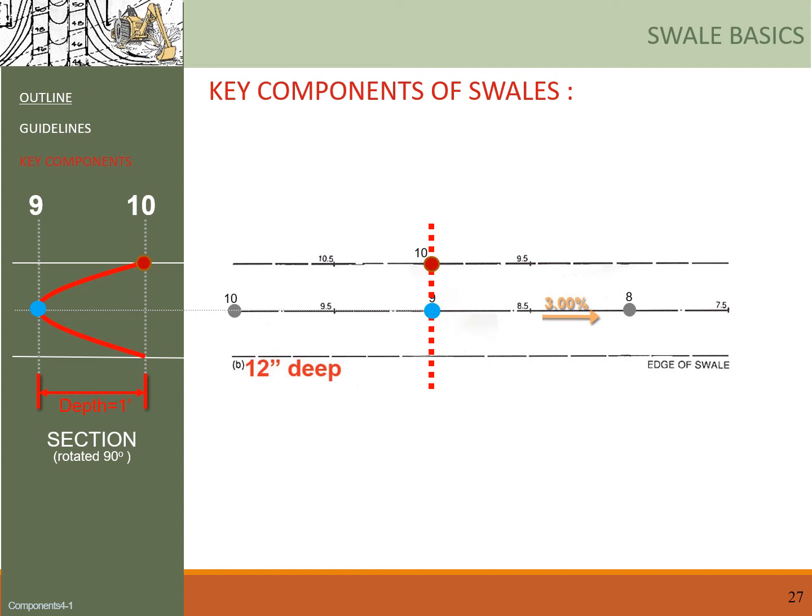And now you know that our 10-foot contour should connect in this way. And because this is a swell with uniform side slopes, you could simply copy the 10-foot contour to find the locations of the 9-foot and 8-foot contours. But you could also follow the same process to find where 9-foot and 8-foot elevations are on the sides and then connect the dots.